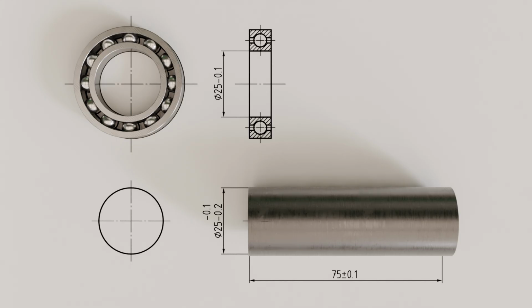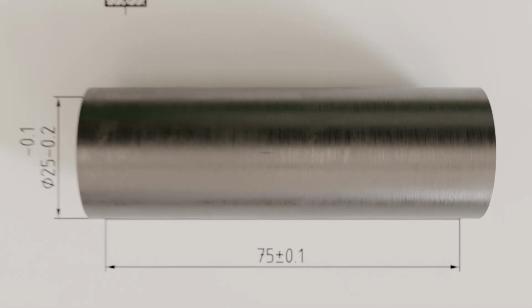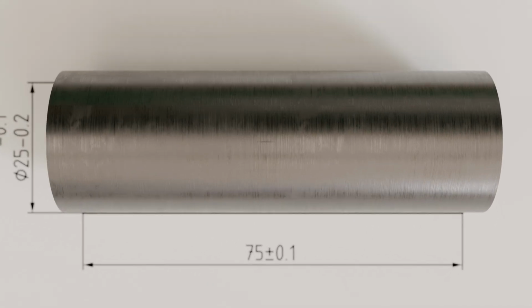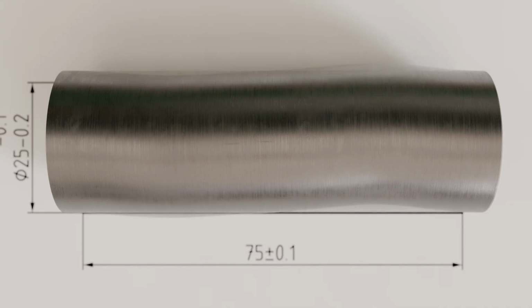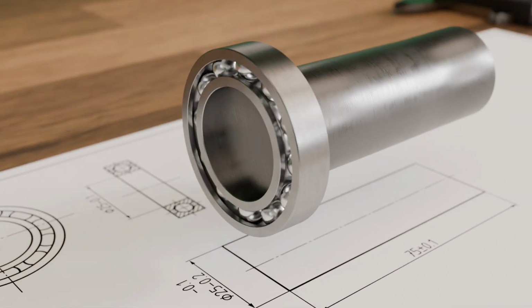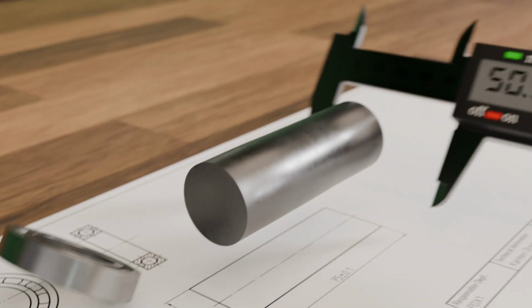For example, if a rolling bearing is to be mounted on a shaft using a clearance fit, the tolerance of the shaft must be chosen so that the outer diameter of the shaft is always smaller than the inner diameter of the bearing. However, simply specifying a dimensional tolerance does not necessarily guarantee that the shaft will actually fit into the bore of the rolling bearing. The shaft can, for example, deviate from the ideal cylindrical form and be curved to a greater or lesser extent. This curvature of the shaft then prevents the shaft from fitting into the rolling bearing, despite compliance with the dimensional tolerance. This deviation from the ideal form is not in contradiction to the dimensional tolerance.